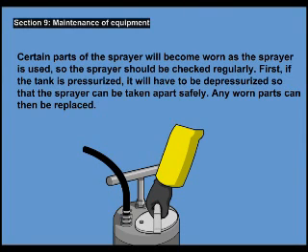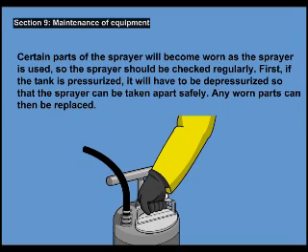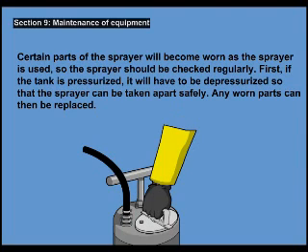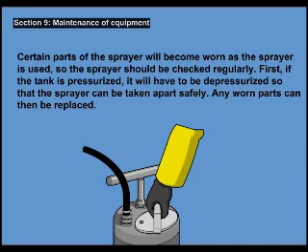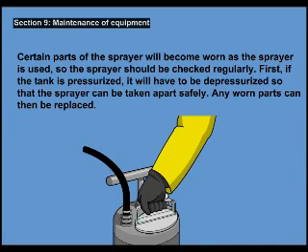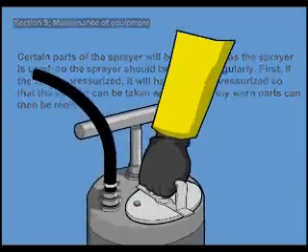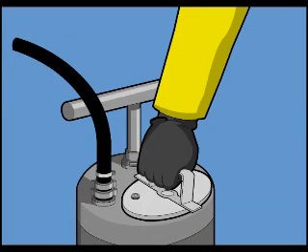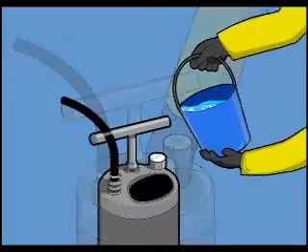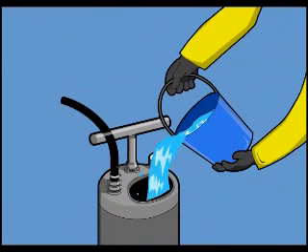Certain parts of the sprayer will become worn as the sprayer is used, so the sprayer should be checked regularly. First, if the tank is pressurized, it will have to be depressurized so that the sprayer can be taken apart safely. Any worn parts can then be replaced.